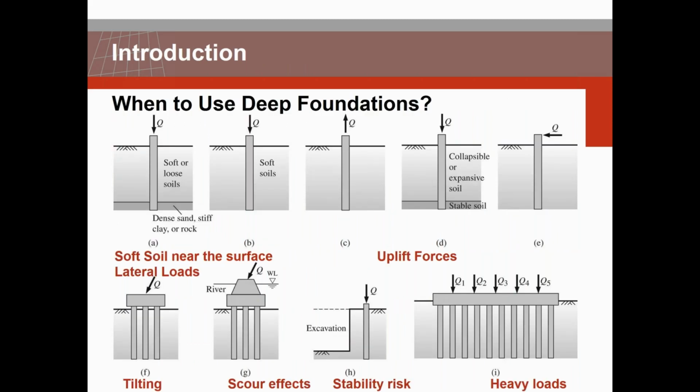When to use deep foundation? If you have a soft soil near the ground surface and it's not able to carry your load, for instance, if you have uplift forces. The same goes for problematic soil, collapsible or expansive soil near the ground surface.